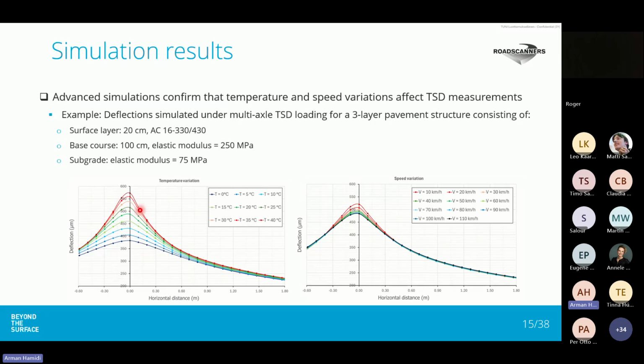So this part is showing the characteristics of the surface layer, and this part is showing the characteristics of the sublayers. So as the asphalt layer was defined viscoelastic, we see that temperature will affect modulus values from the asphalt layer, which is shown at inner radial distances.